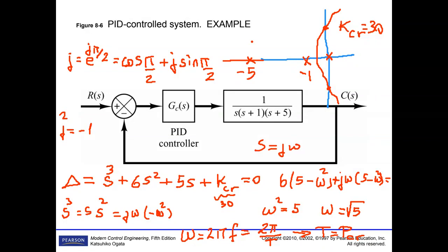Thank you, John. I think we first have to add a step block. Step. Okay. And connect it to the transfer function. And to see the result, we have to put a scope block. Scope. Yeah. Here. That's for basic.